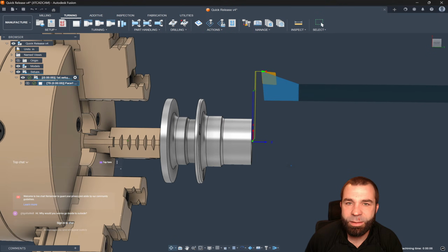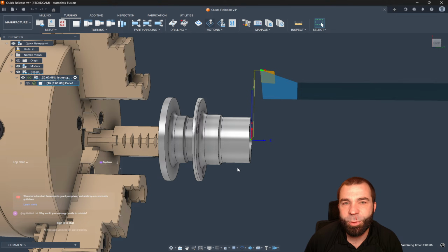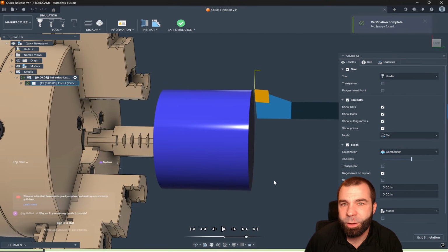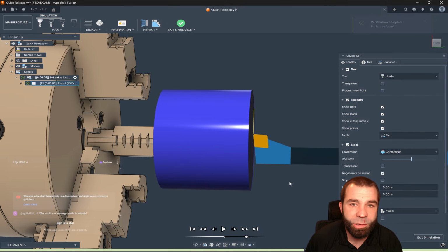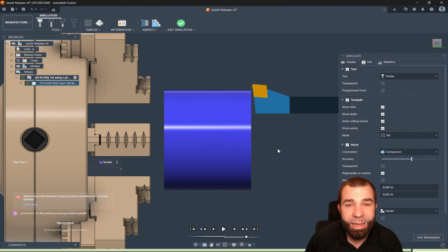And just like that, in this case, if I was to simulate this, you would notice that we have that ability again to work from the inside profile outwards. Again, chip loading and feeding into your tool based on your tool angle, your insert angle. But as such, again, inside to outside can be very handy based on the order of operations.